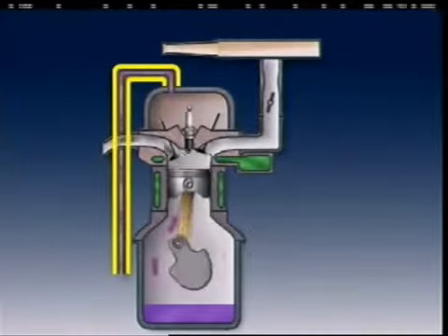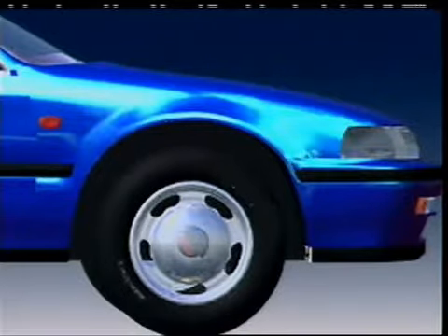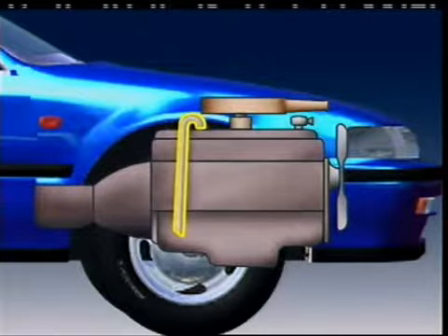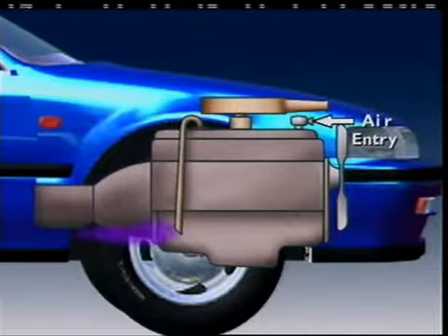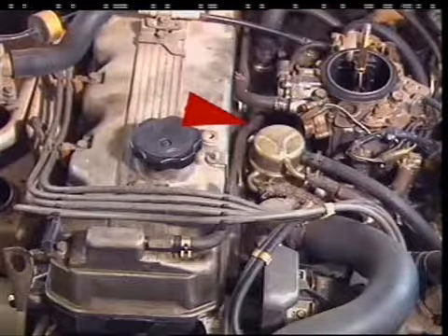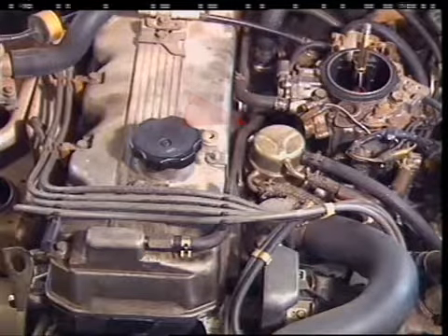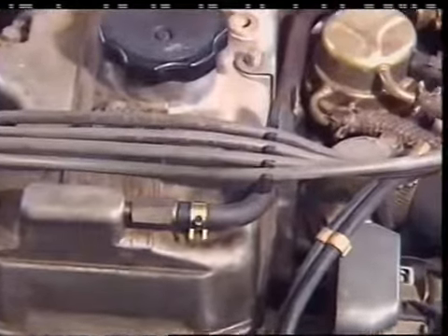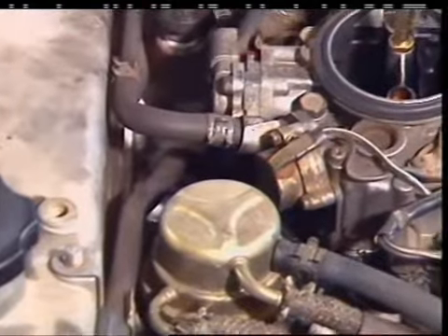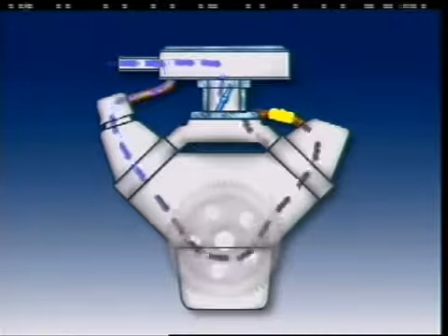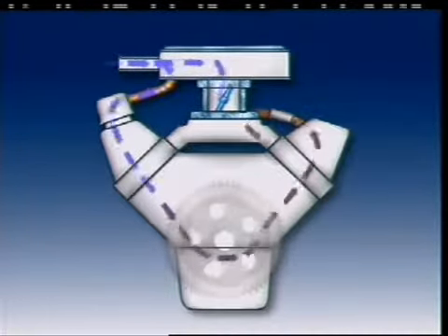To prevent pressure build-up, the crankcase must be ventilated. In older vehicles, crankcase vapours were vented directly to the atmosphere through a breather tube or road draft tube. It was shaped to help draw the vapours from the crankcase as the vehicle was being driven. Modern vehicles are required to direct crankcase breather gases and vapours back into the inlet system to be burned. A common method of doing this is called positive crankcase ventilation, or PCV. A valve called the PCV valve regulates gas flow between the crankcase and the inlet manifold.